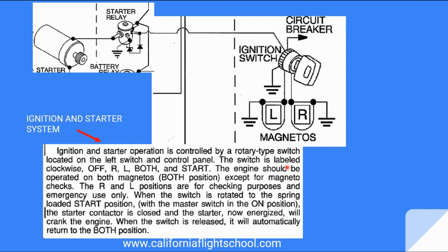Is there hand propping? Is there an external plug that could help us with the engine start? Things of that nature. So you would start at a very broad overview on how it's all working together, and read that chapter, and then figure out maybe failure modes, or what to do if a starter or a battery, let's say, would not work.